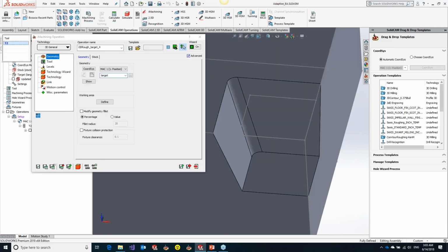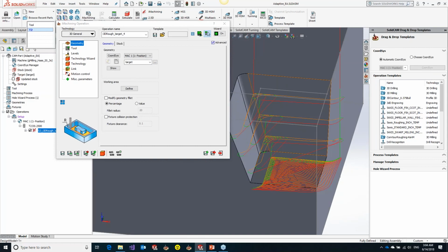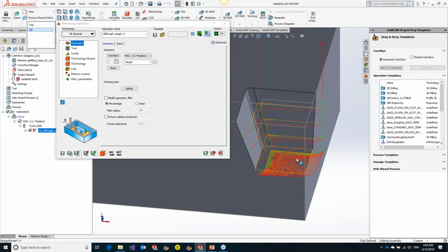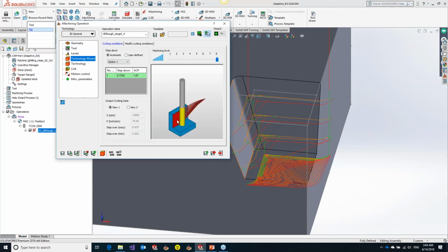Okay, so I have a simple toolpath here, just for cutting the semi-open pocket area. And what did we do? As everybody knows, we have the engagement angle that you get from the wizard. This is calculated on the depth of cut. Our depth of cut is 0.7 inches, which is about 18 or 19 millimeters, and we have an engagement angle of 38 degrees.